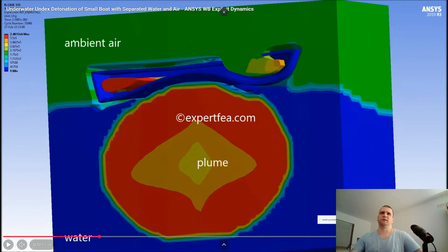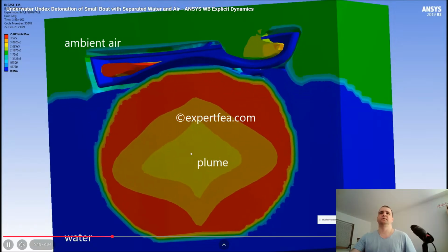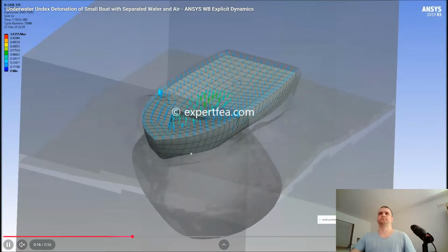The more Eulerian cells, the finer the Eulerian discretization, the smaller the gap will be, because it will approximate better the cavity that it fills. So a solution to decrease the gap would be to refine and increase the number of cells for the Eulerian domain, for the Eulerian body.